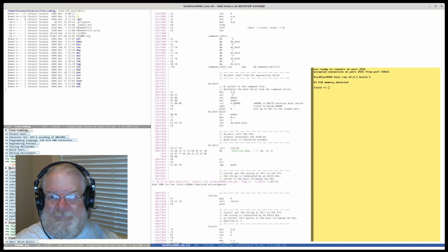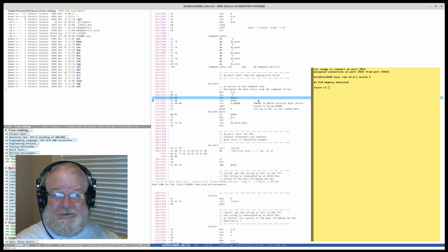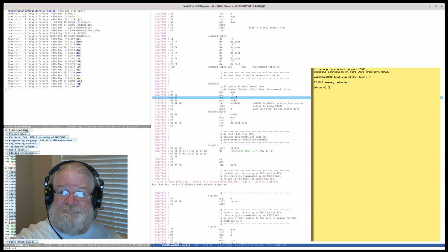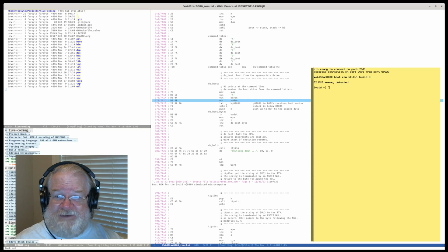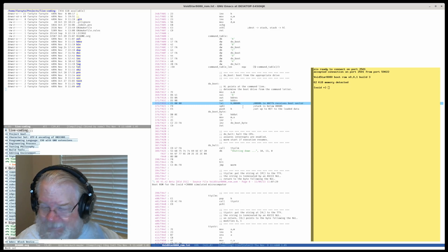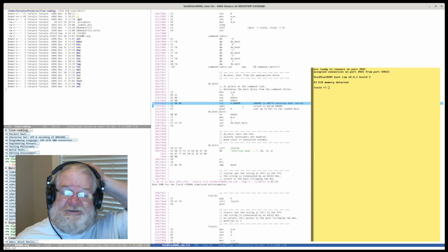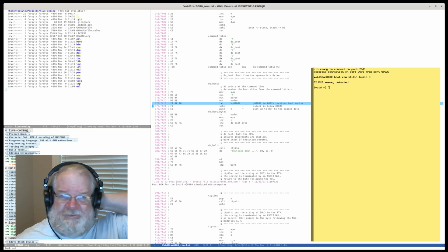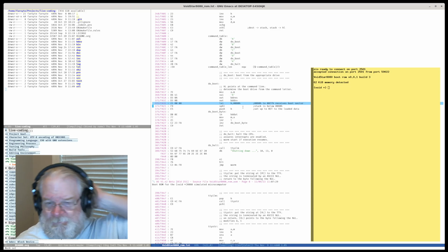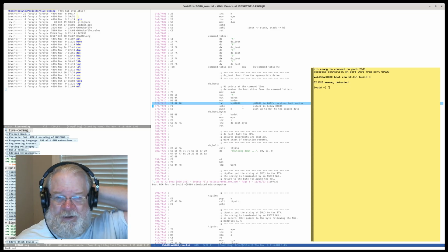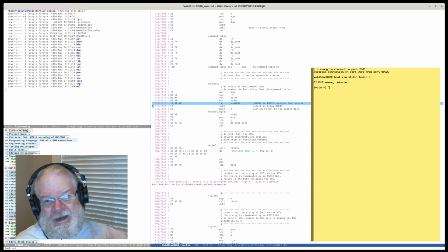Do boot. Basically, we reset the simulation. We reset the simulated disk controller, in case the disk controller has internal state that we need to reset, this code doesn't get to know whether we do or not. Set the drive, pick an address, which I'm arbitrarily putting at 80 hex. So we're not going to touch the first 128 bytes. That's where RSTs jump down into 0 and all the way up to just below 40 hex. It's kind of convenient to put it at 80 hex.